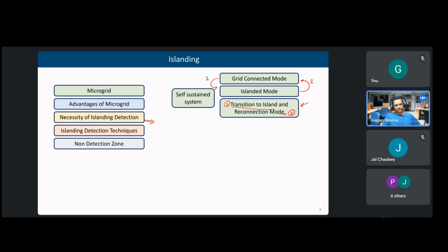Let us discuss islanding. So islanding can be both intentional and unintentional. And when we talk about these islanding detection techniques, then we are focusing on the unintentional. Because intentional, we know we are doing it. This is already planned, and if not planned, then as per the contingency, we already have a systematic plan to do the systematic separation of the main grid to avoid major breakdowns.